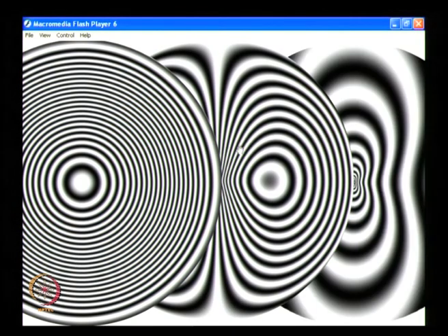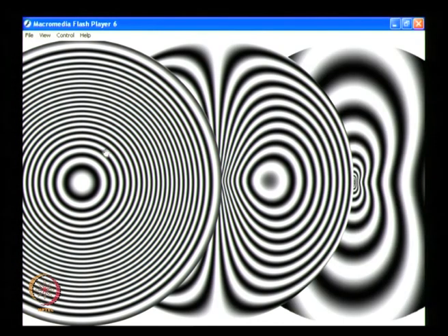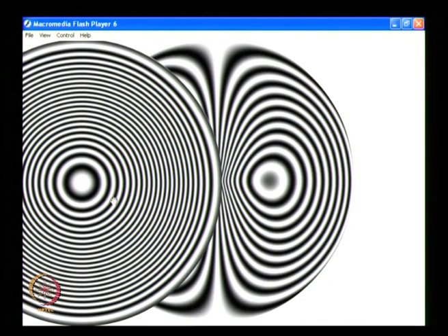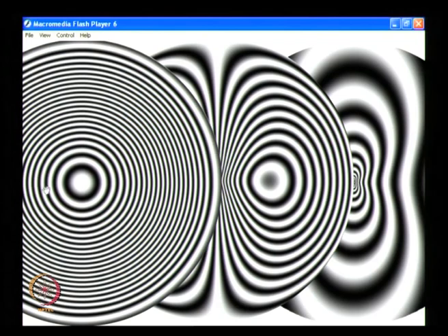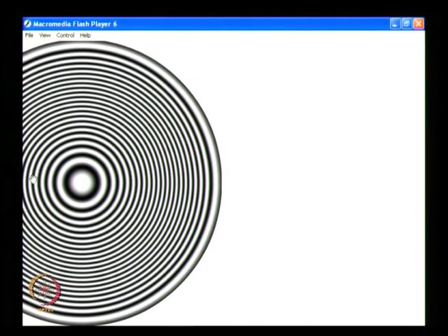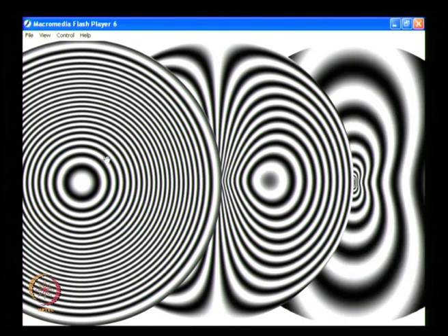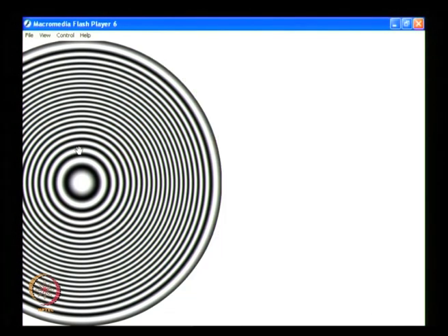Now, you know that this is the slope, this is the curvature information, and each of these requires separate optical arrangements, and you may be able to get these displacements by the technique of holography or speckle interferometry or shadow Moire. What you see is the simulated fringe patterns, and when you really make an experiment, the fringe patterns will follow this closely, but the quality of the fringes depends on the technique being used.